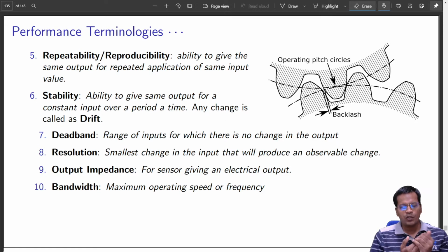If it is a transistor, your switching should not be very fast. If it is very fast, after a certain frequency it will directly give you 1 or directly give you 0 all the time. It won't change along with the input change. That is one example. That is the reason you switch to UJT or some MOSFET switches. So that was the reason, and the same is the reason here.